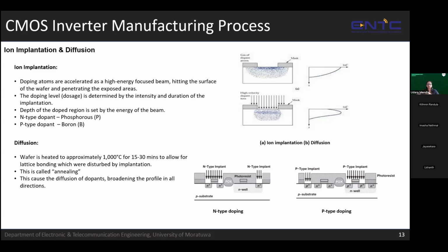And in this process, once again, the lattice structure comes into its form, and it also helps the dopant atoms to diffuse further and spread evenly, because it's a very natural process. Whenever you have thermal energy, we know that atoms and electrons and everything move freely and go to their equal positions. So that's why we do this annealing, and the whole process is called diffusion, or diffusing everything so that we get a deeper and well spread N well.